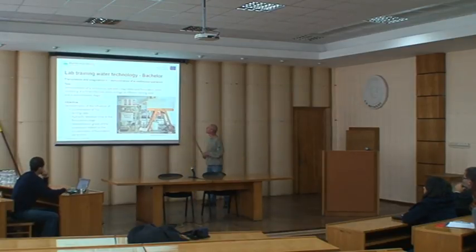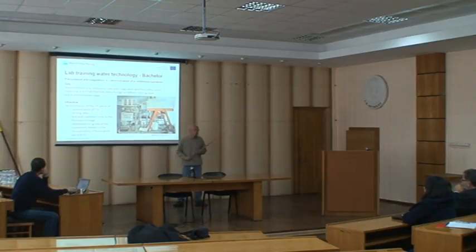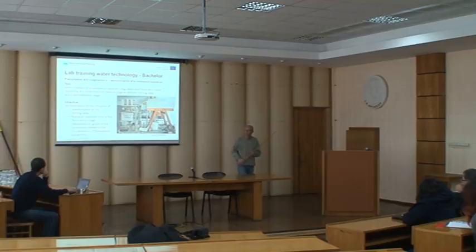It's a continuous operating system for the flocculation. So we have 3 chambers here, stirred at different speeds, from very fast to very slow, like it's done in practice. And then the sedimentation basin over here. This was not under operation, therefore you can see no effect, but I took a picture of this just to give you an impression of what we are doing in Höxter.